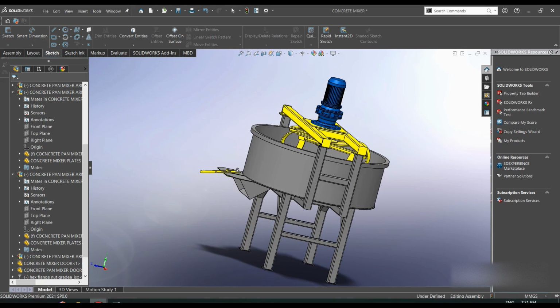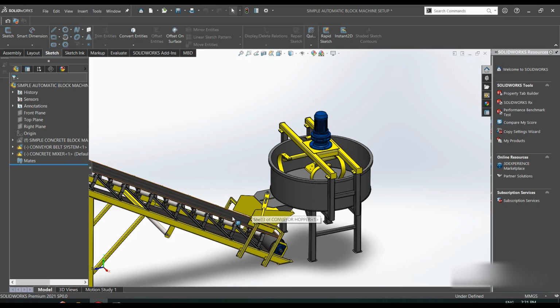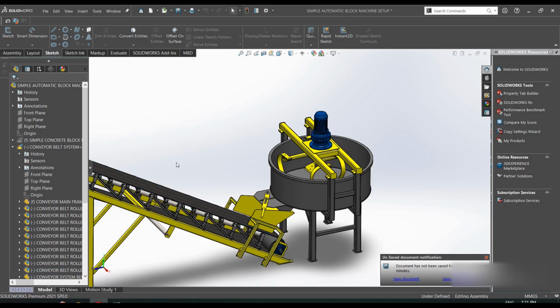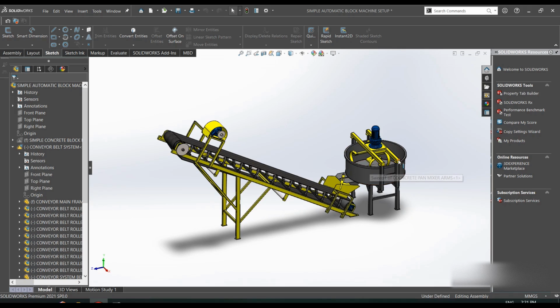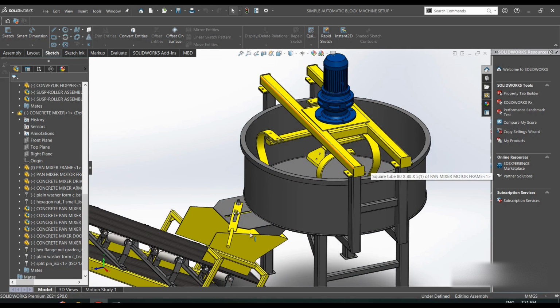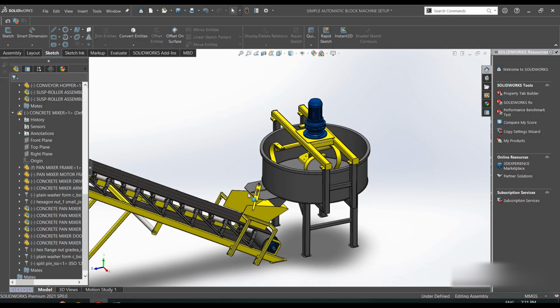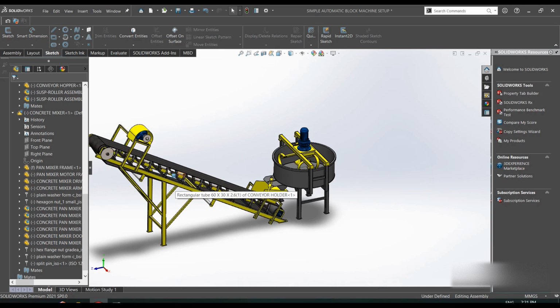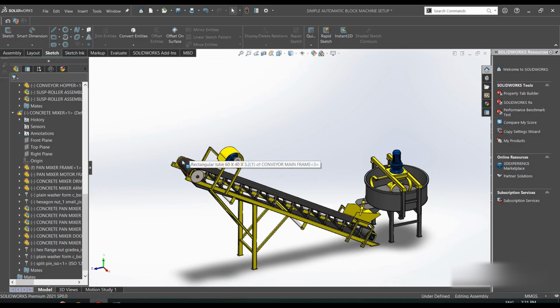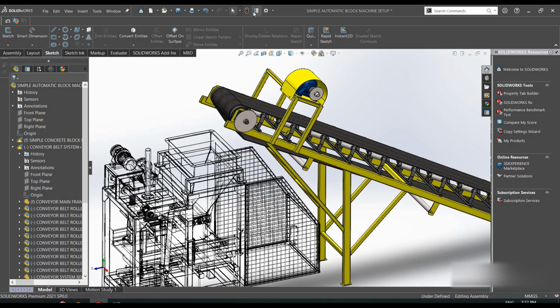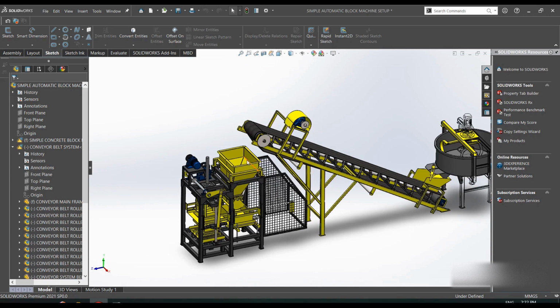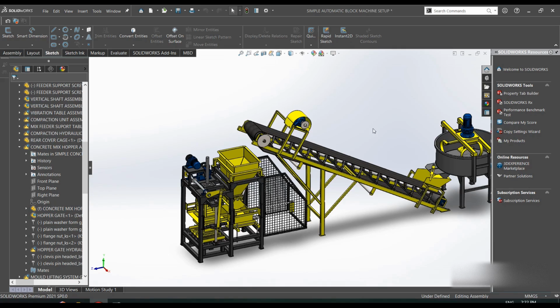through down here, and through that into this hopper here and onto the conveyor belt. So basically this is how the system works. When you have your materials for making the concrete blocks, sand, cement, and the water, you pour them in the pan mixer. The pan mixer mixes them. Then you open this gate here. Sorry, this is fixed. So you open the gate, the mix pours here, then it is taken up the conveyor belt to the block making machine, into the block machine hopper here. So that's how it works.